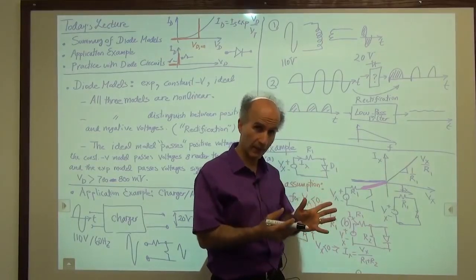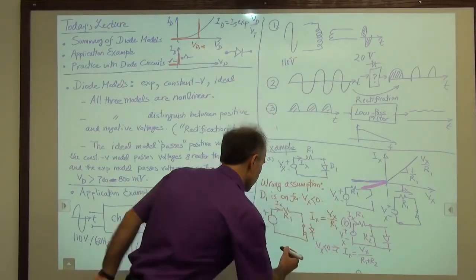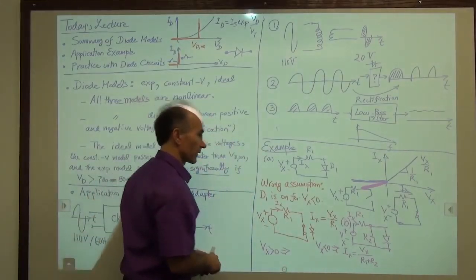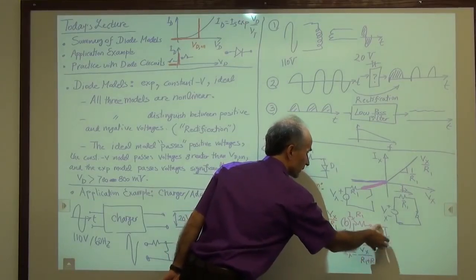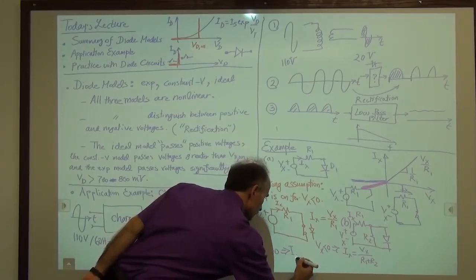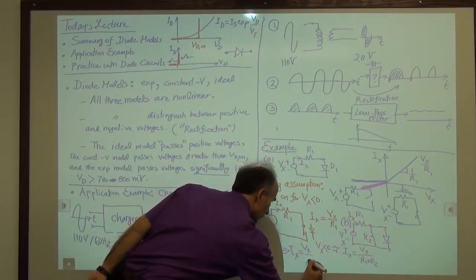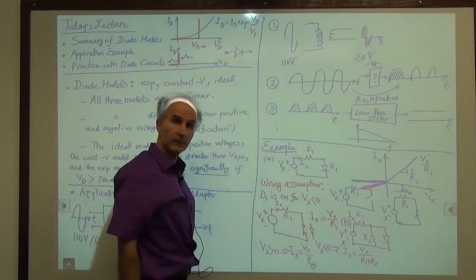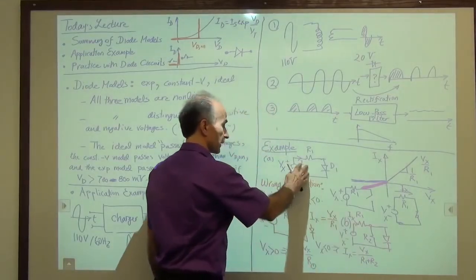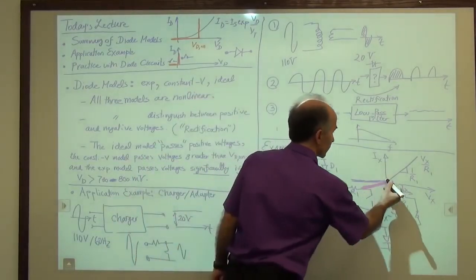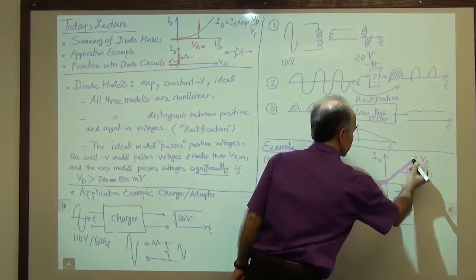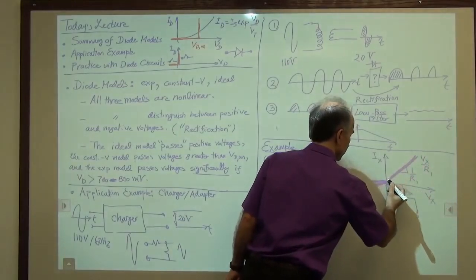The zero resistance dominates. So if Vx is greater than 0, then the circuit reduces to just R1 and the short circuit, like before, R1 and the short circuit. So we see that Ix is just equal to Vx over R1. So interestingly, for a positive Vx, this circuit and this circuit have the same current. So that current will just coincide with this one. I'll just draw it next to this one here. Okay, so these two coincide.